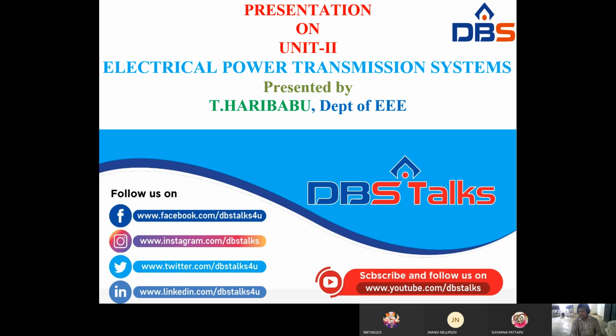V2 equal to Z21 I1 plus Z22 I2, right? Coming to the Y parameters or short circuit parameters, the input and output currents I1, I2 may be expressed in terms of V1 and V2. I1 is equal to Y11 V1 plus Y12 V2. I2 equal to Y21 V1 plus Y22 V2, right?